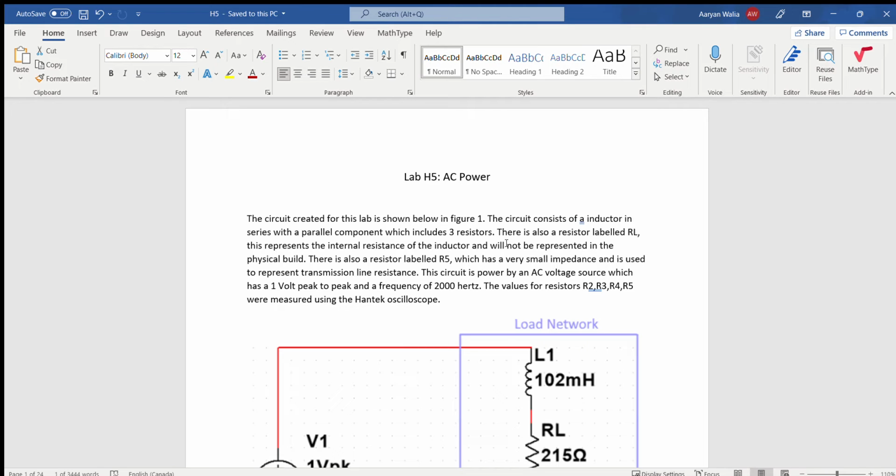So to fix this, they use a technique called power factor correction. Basically, just hook up a capacitor in parallel, and that can cancel out the reactive power, and it ends up supplying current to the load when the inductor fails to do so. This makes it so that there's practically no interference, and you end up saving energy and money. So in this lab, we're going to explore how to do this.